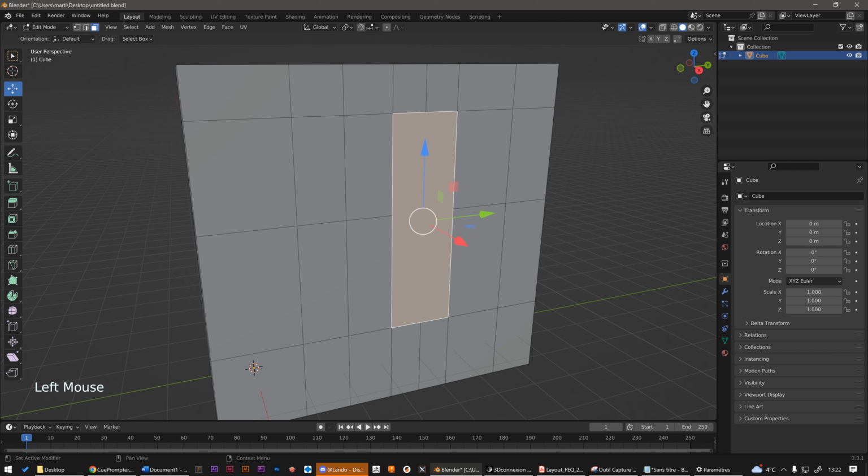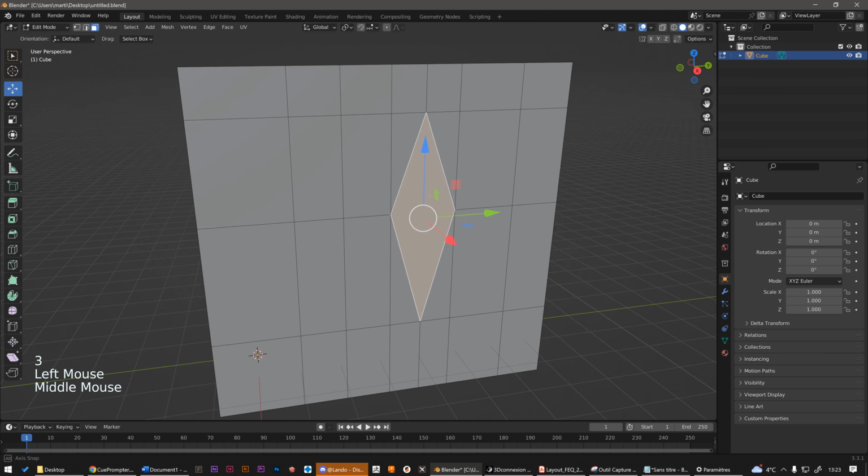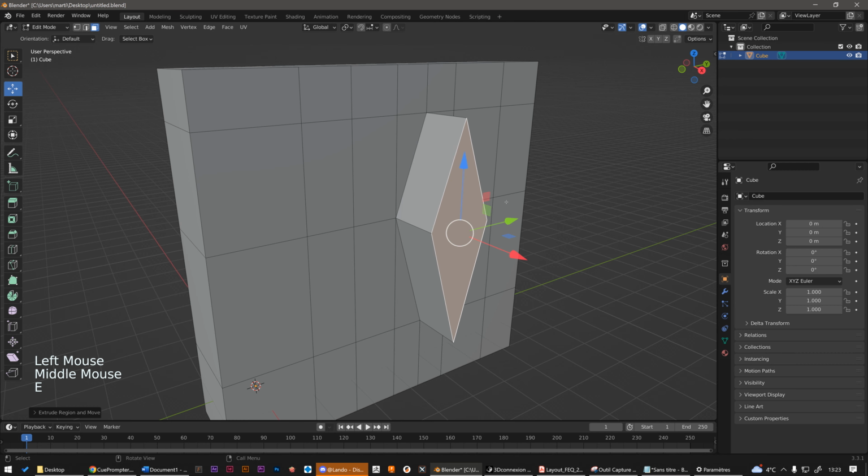It's just to show you the tool, but we could imagine that we wanted to insert a gem or a diamond in our topology. So, to insert a face with a diamond shape within a quad topology, we first need to change the topology. And for that we should have dissolved some edges, as we just did. This is allowing us then to draw a diamond with the knife tool. And now we can simply extrude the face to add the diamond shape detail.